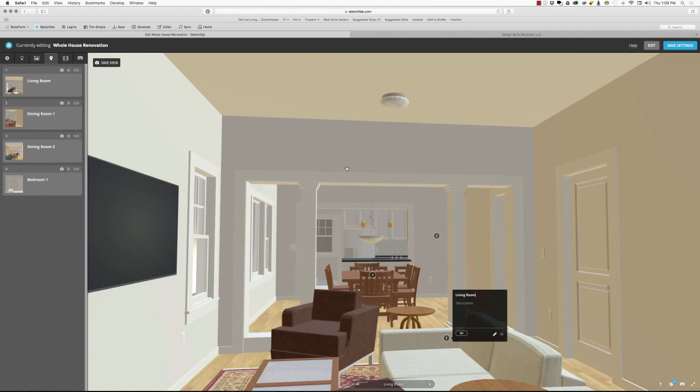Now, a point with sketchfab.com with free accounts is that you only get 5 annotation points. You're limited at 5. If you want to pay for a subscription, I believe that you get unlimited annotation points. All right, let's click OK. Save our settings again. If this were a brand new upload, there'd be another button up here entitled Publish. Initial uploads are drafts first and not visible to the general public until you publish them. So once you've saved, click on Publish, and that will be done there.